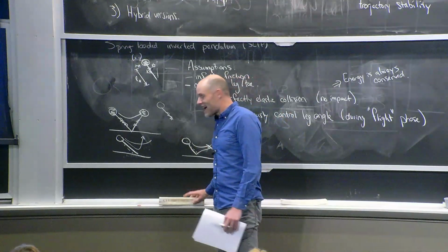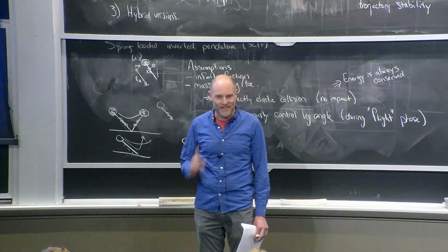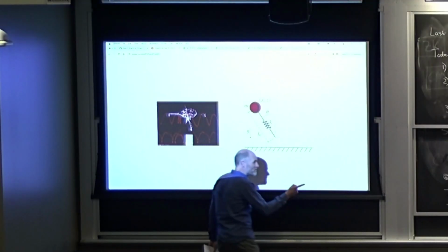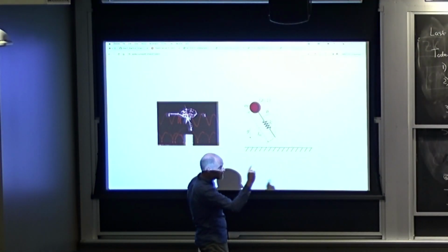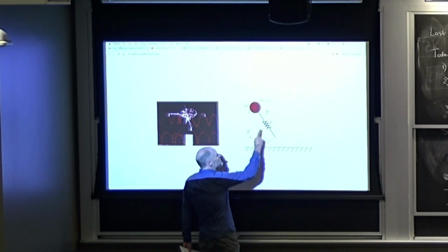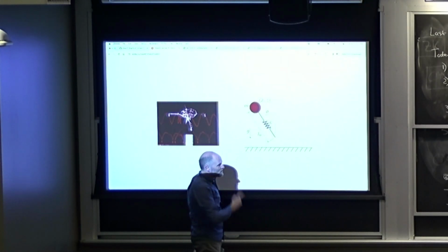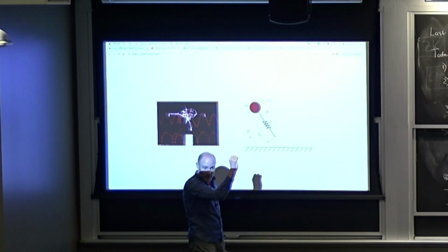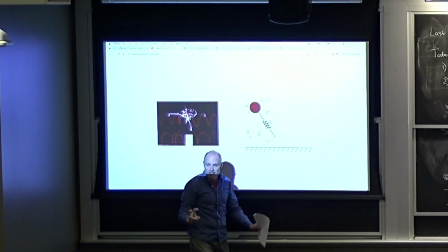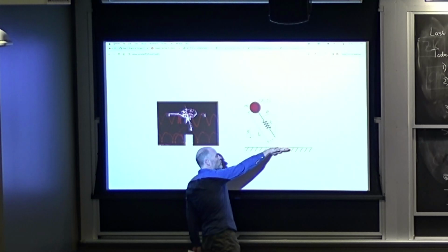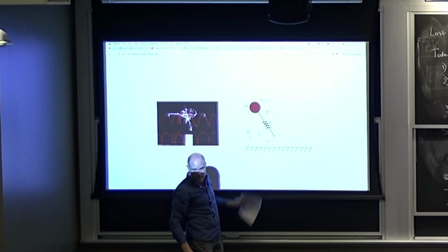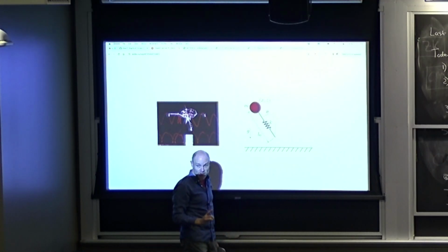Now, it turns out the reason that the deadbeat controller is so awesome for the SLIP, okay, so in both of those cases, in order to evaluate P, whether it's for LQR linearization or for the deadbeat controller, it means you have to know sort of X, and I used Z here, I'm sorry, I used Z here and Y on the board. You need to know your height of your object and maybe its velocity, for instance, at the apex. Implicitly, what that means is you have to know where the ground is, because I'm defining Z as the distance to the ground. Okay, here's a really cool trick.